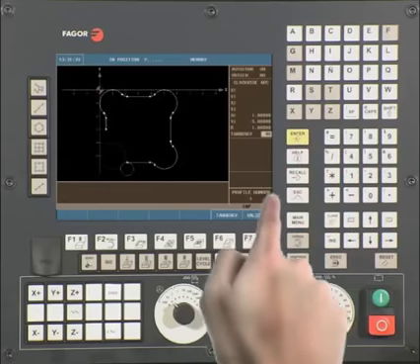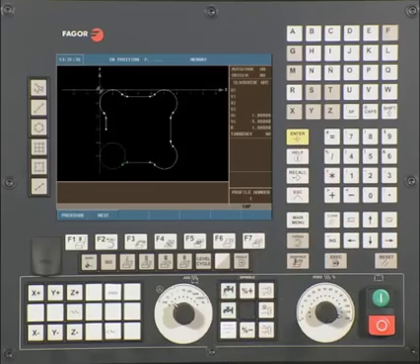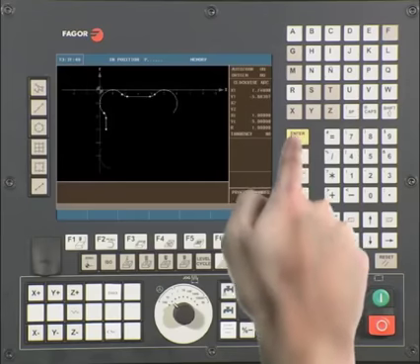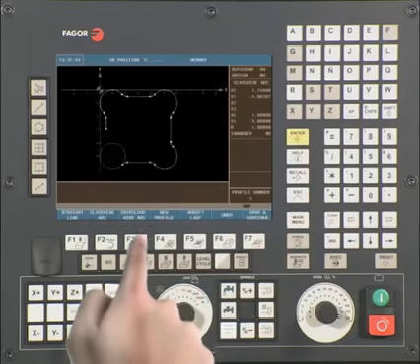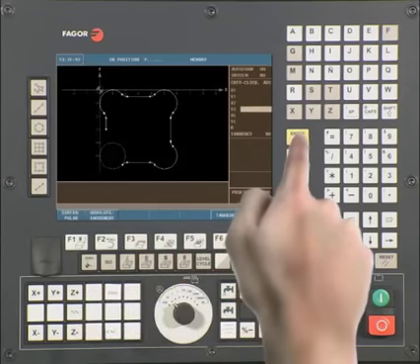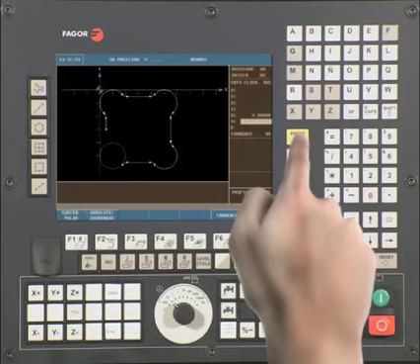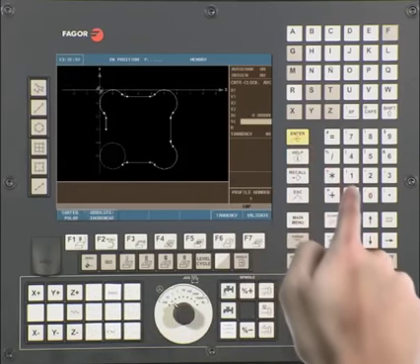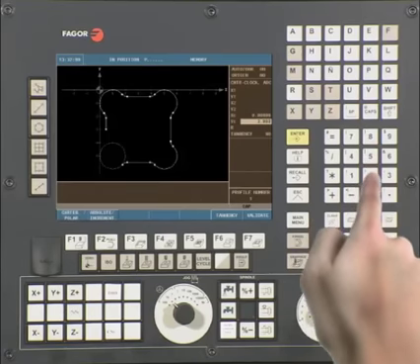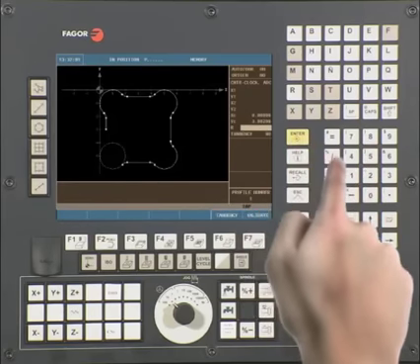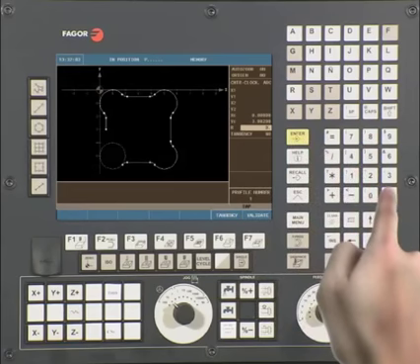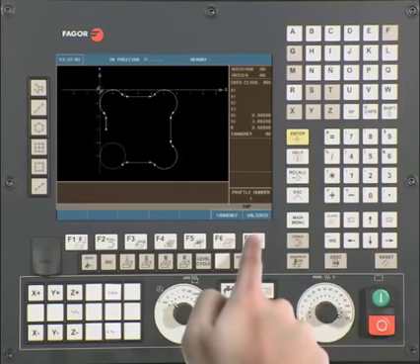Validate the data. There are multiple intersecting points with this line or arc. The CNC will prompt you to select the correct intersecting point. Press Next to see the different intersecting points. Press Enter to confirm the correct one. Select counterclockwise arc. Our center on XC is 0. Our center on YC is -3.882. The radius is 0.5.